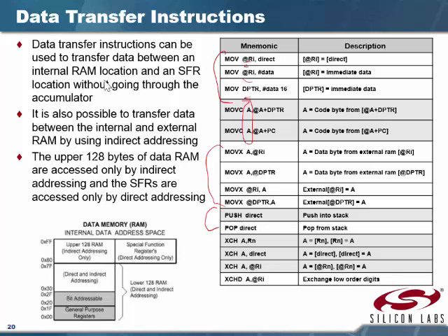That there, and you've got to be somewhat careful because, especially if you're writing in C and you have a lot of function calls, then you can overflow the stack without realizing it, because the number one thing that uses the stack is whenever you do a function call, it pushes onto the stack the return address. It also pushes onto the stack any variables that you pass to that function. It also pushes onto the stack the return values of anything you've got there.